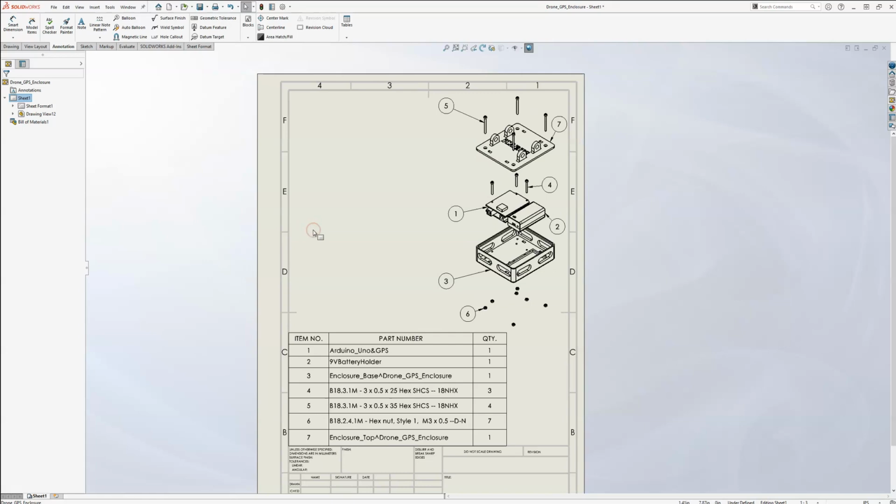Very quickly, we've been able to take that exploded view that was inside the assembly. We created a 2D drawing that referenced that assembly. Then we said, okay, I want to look at that exploded view, which got us all the geometry. Then remember, we went to the annotation tab, went to tables, and created the bill of material table here. Did a little bit of customization there, right? We deleted a column out. We made this column a little wider. You could also insert custom columns there as well and have that really driven by custom properties of the parts if you wanted to get a little more sophisticated there. And then finally, we used these balloons in order to identify the parts in our exploded view.